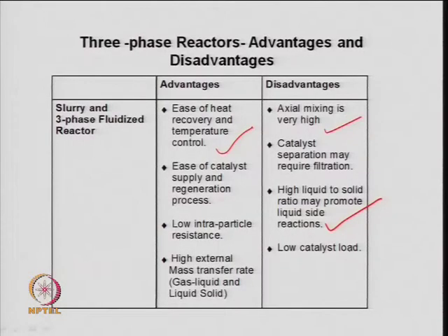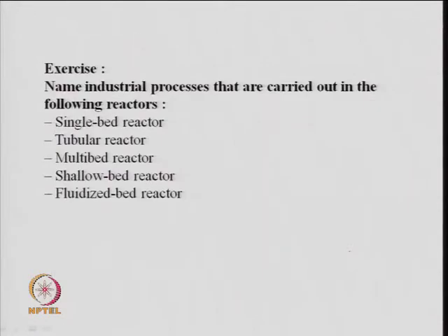A high liquid to solid ratio may promote liquid side reactions. Here the liquid volume is high, so the liquid to solid ratio is high. It means there may be homogeneous side reactions, secondary reactions that may happen in the presence of a high volume of liquid. And catalyst loading per unit volume is low. That is again an issue here.